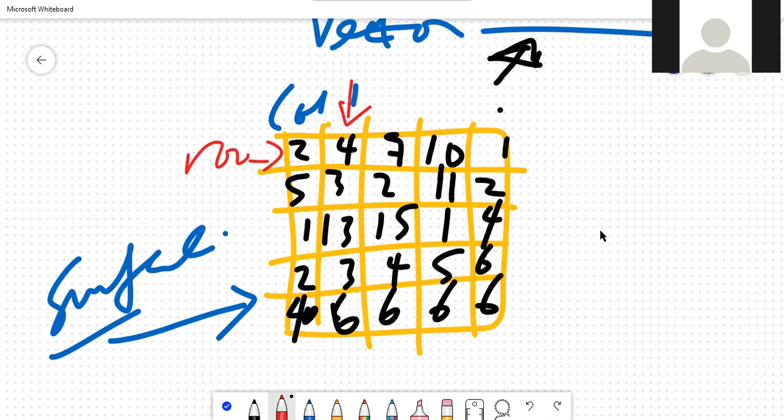In a viewshed, all we are doing is asking: if I'm at 1, can I see 15? Anybody watching this video, ask yourself the question: if you're at 1, can you see 15? No, you can't, because it's blocked by 11. So 15 is not in your viewshed. 11 is in your viewshed, well, it's blocked actually, and 2, 1 is also blocking it. So virtually you end up not seeing beyond this area.